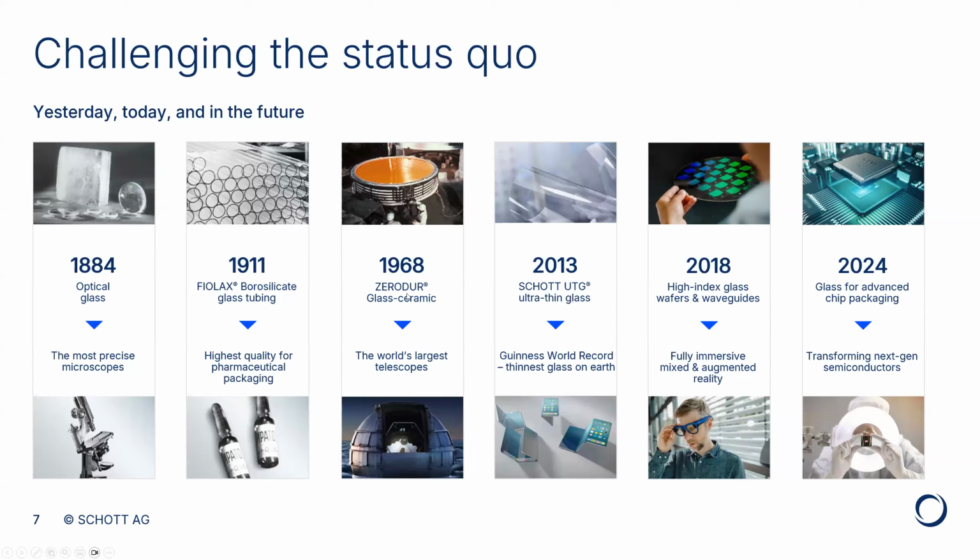Glass ceramics are another really interesting material. So there you first make a glass, and then you seed inside this glass a crystalline phase with negative thermal expansion. And you try to balance the amount of the negative expanding crystalline phase and the remaining positively expanding glass phase in such a way that they add up to exactly 0 thermal expansion. So there's different variants of that.